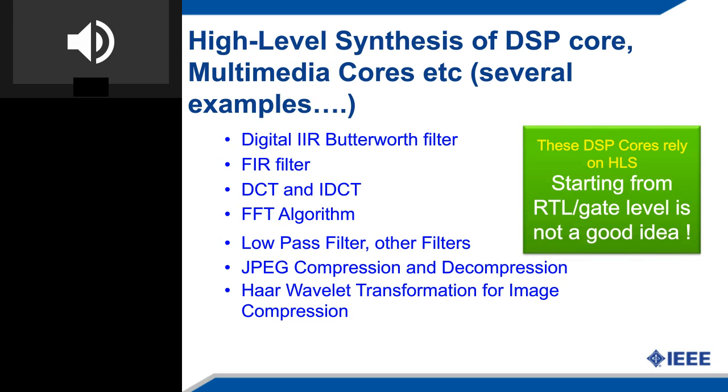DSP and multimedia-based reusable IP cores form the key components of SoCs in consumer electronic devices, and as we know, these devices are involved in the global design supply chain process, which makes them very vulnerable to security threats such as IP cloning, IC cloning, false claim of ownership, and so on. I would like to specifically discuss two major branches of IP core protection. First is known as digital signature, and second is known as IP steganography, which is quite effective in securing IP cores. Before I go into that, let me talk a little bit about the hardware threats.